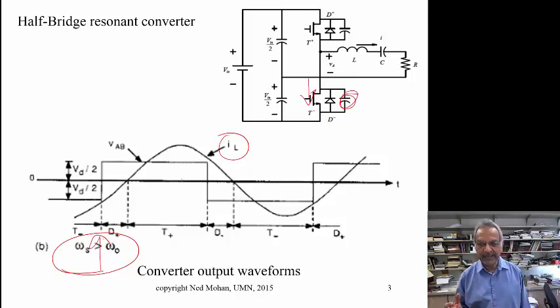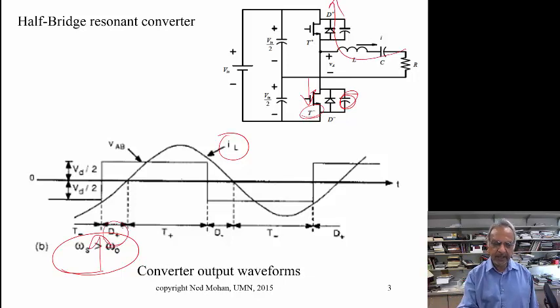So it's really a 0 voltage turn off for T minus, and then when we turn this transistor off, this current being negative is flowing through D plus as shown here, and only after it's flowing through this anti-parallel diode in the reverse direction do we apply a gate pulse to this upper transistor, and so it's turning on at 0 voltage.